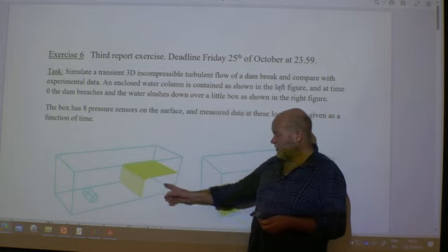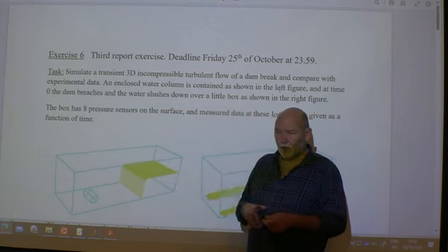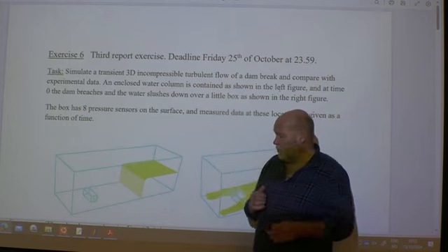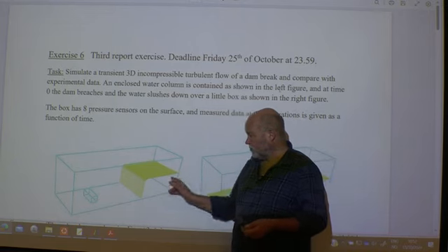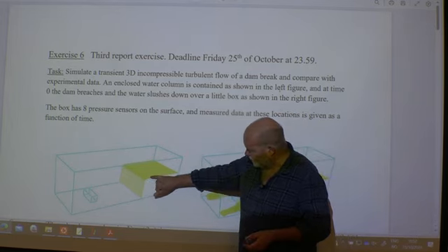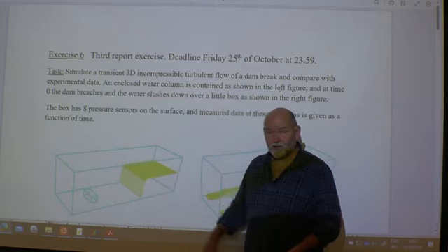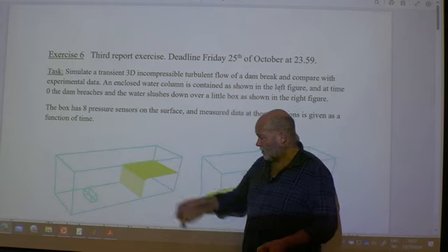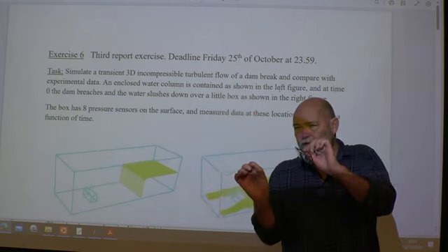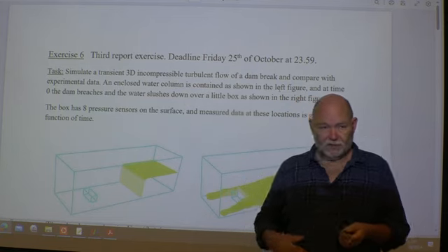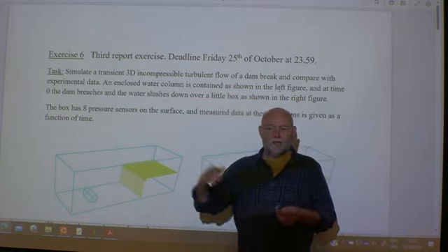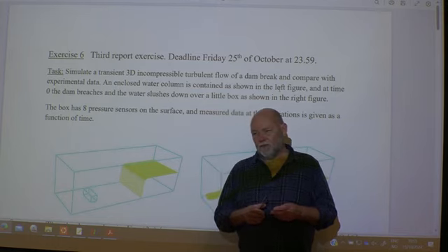So it will calculate 1 is water, 0 is air. 0.5, we have somewhere in between, inside one single cell, but you don't know exactly where. But it will actually track the surface quite nicely. Although here, in this initial state, you can see a small curve. That shouldn't be there. It should be a square block. That is due to paraFoam interpolating from center to center. So it's a cosmetic thing, don't worry about it. But no, we don't have the correct interface tracking here. Would be fun, but no.